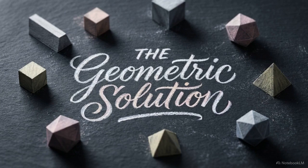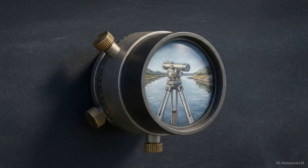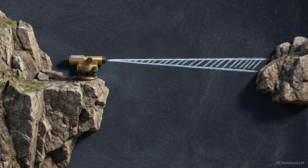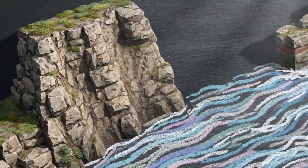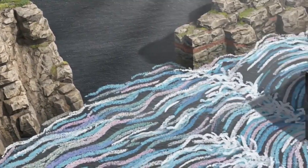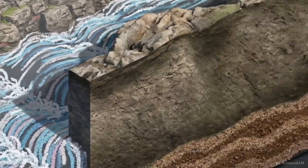This is where we introduce reciprocal leveling. It is a symmetrical surveying procedure designed specifically to bypass the unknown distance problem. The core logic relies on physical mirroring. By taking a pair of readings from one side of the obstacle and then crossing over to take a mirrored pair of readings from the exact opposite side, surveyors exploit this structural symmetry to perfectly cancel out the unknown variables hidden within the massive, impassable gap.